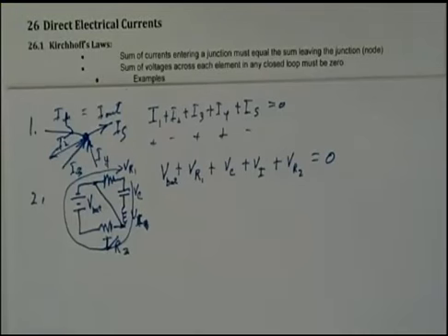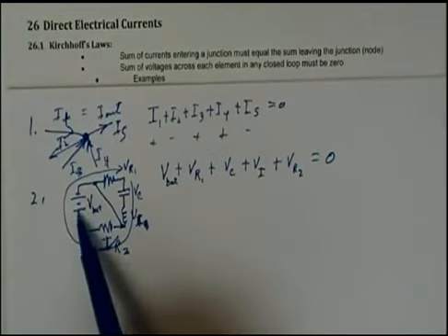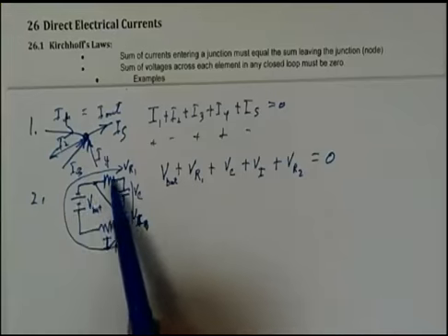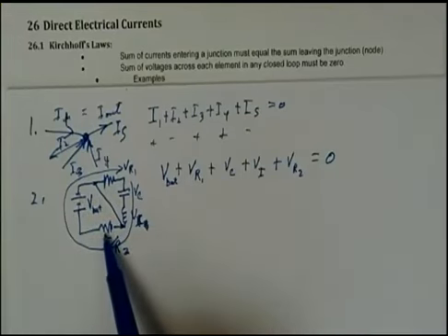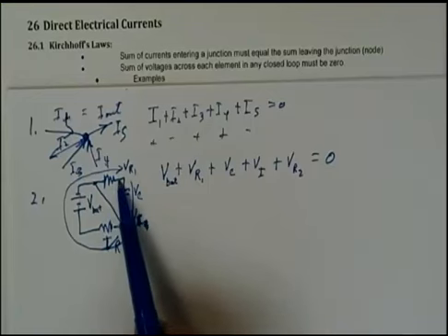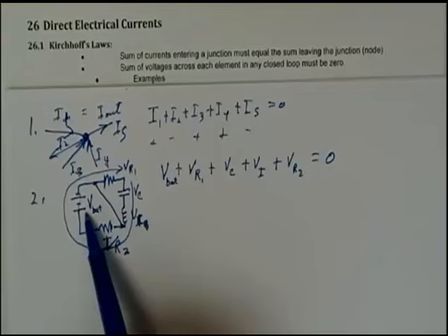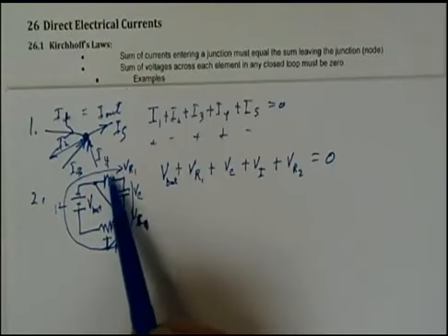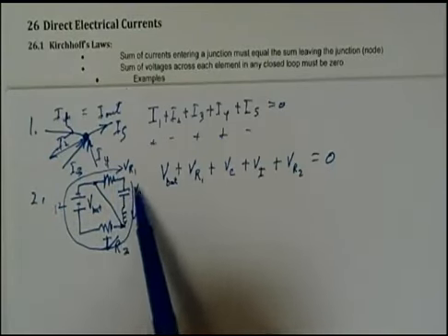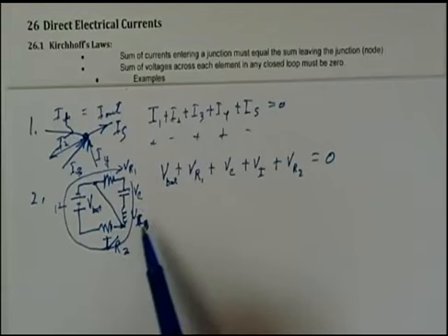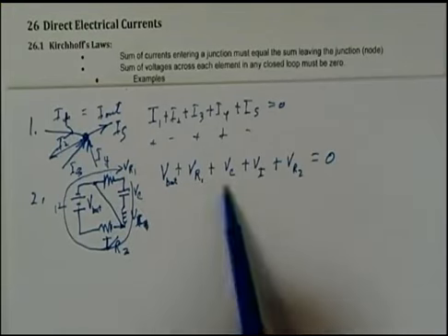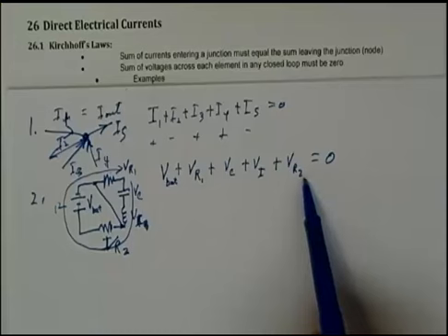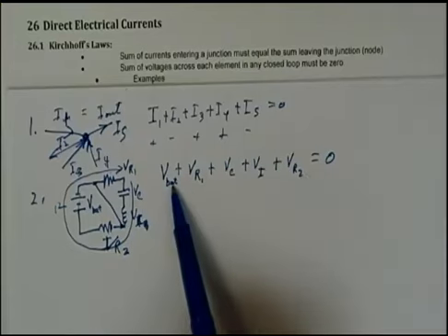Now the sum of those can only be 0 since we have a positive voltage across the battery if some of these other voltages are negative, and in fact they are negative. They're negative because they have a voltage drop that's in the opposite direction of the battery. And so the battery puts a voltage in one direction. This might be, say, a 12-volt battery, and these might be a -2, a -3, a -3, a -2, whatever, but these other voltages have to add up so that they exactly cancel the voltage of the battery.